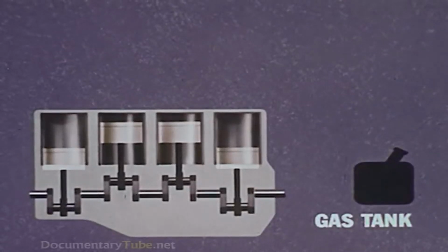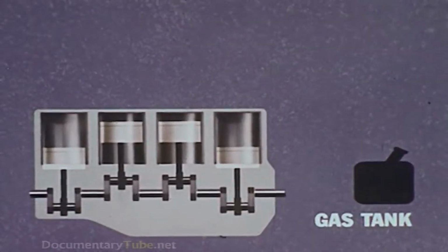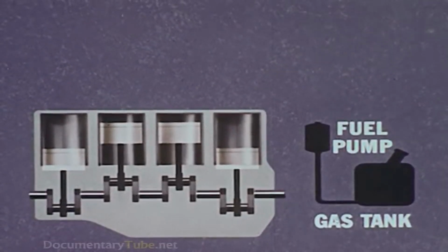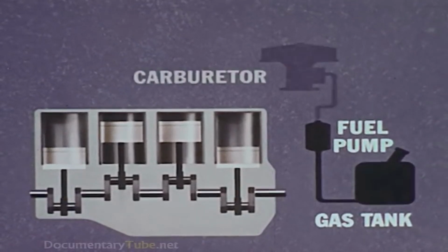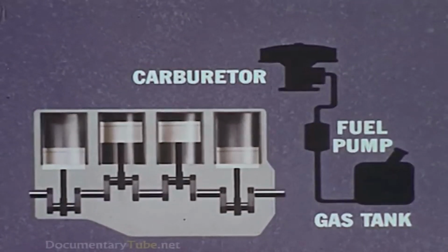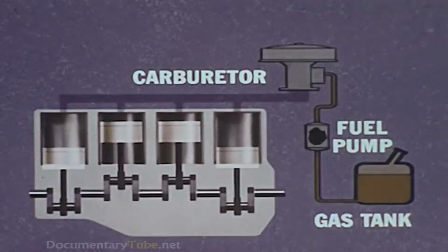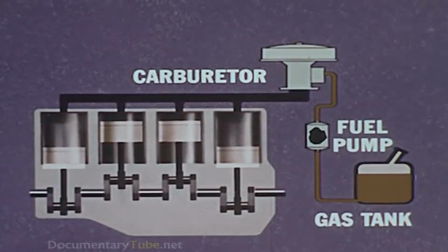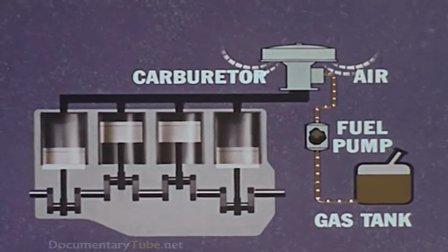The camshaft, geared to the crankshaft, lifts and lowers the valves in the cylinders. Now the right and left cylinder heads, containing the valves themselves and the valve lifters. The distributor at the rear of the engine is also driven from the camshaft. Now the fan, the generator, and a part of the cooling system.